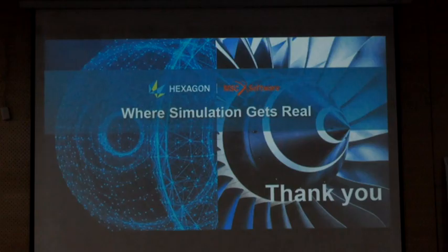Where there is only overhang, there we use cone. Further, you can optimize using local support. Instead of giving support from the base plate, you can give local support as well. For that you have a lot of software like AM Studio, Magics, even Simufact. Those software need to be used for support optimization.